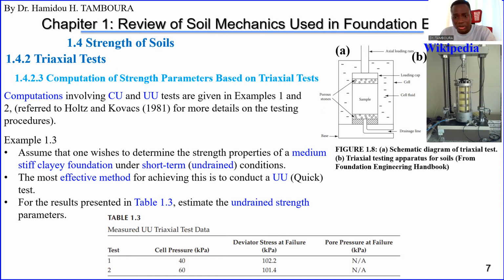The water will support it. I will explain this more later, but this is what makes the difference between the UU test and the CU test we did before. If you remember in the previous example, in the previous video, these values were not the same.